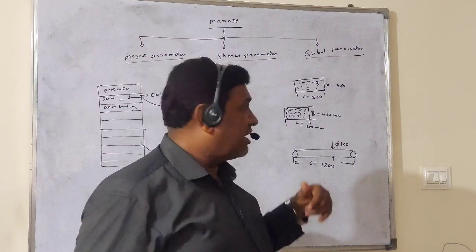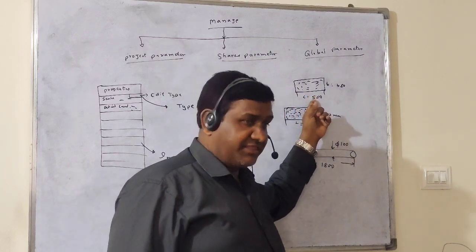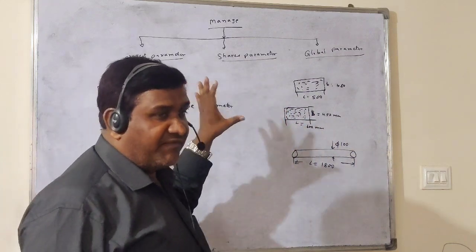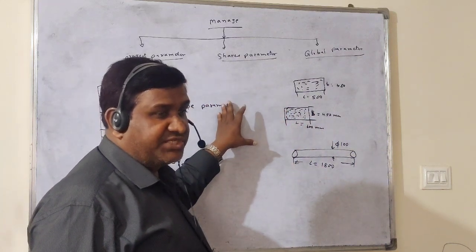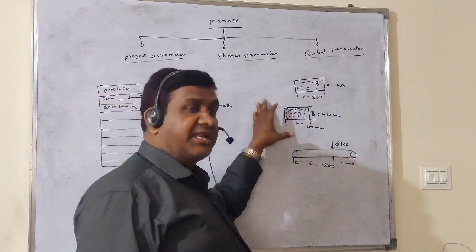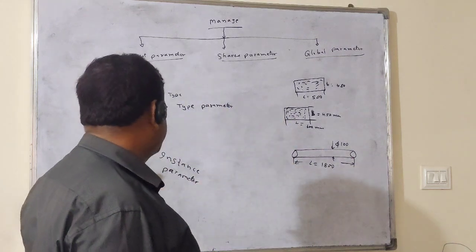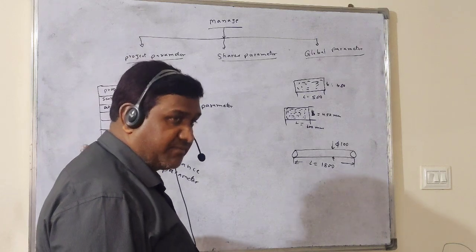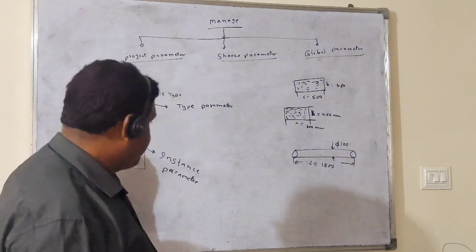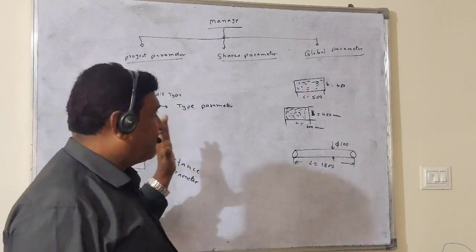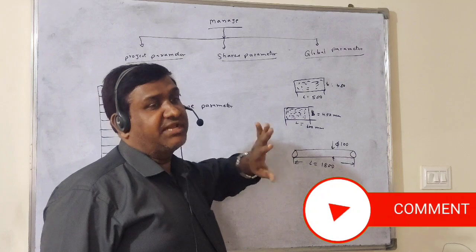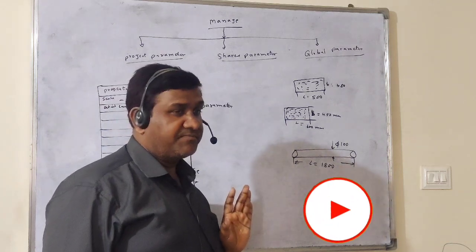Got it? So now I have to change the column length. Initially, whatever length and width values we have given here, those values directly affect the properties toolbar. If you change directly in the properties toolbar, only that particular entity is going to be changed, the remaining ones are not going to be changed.